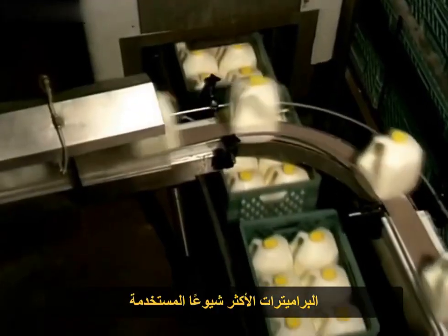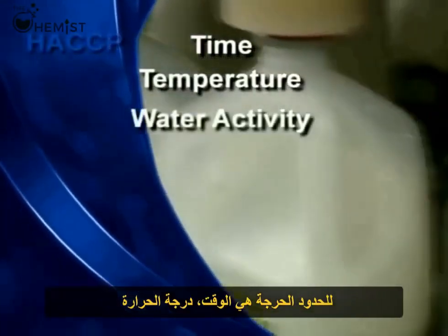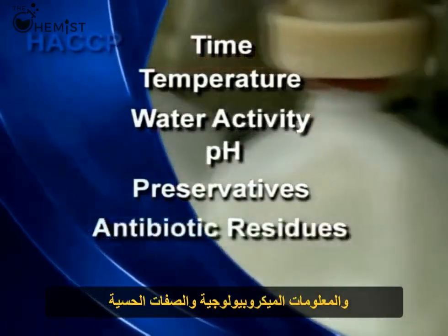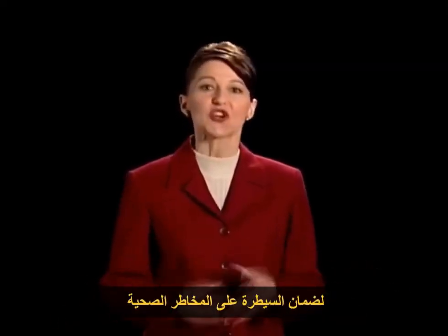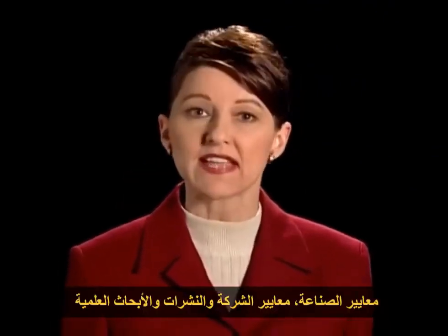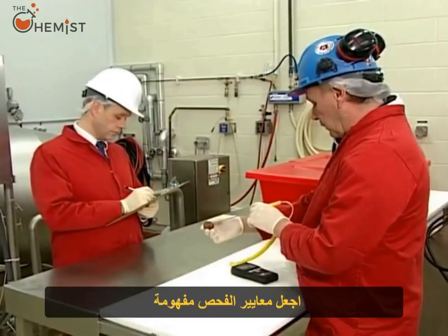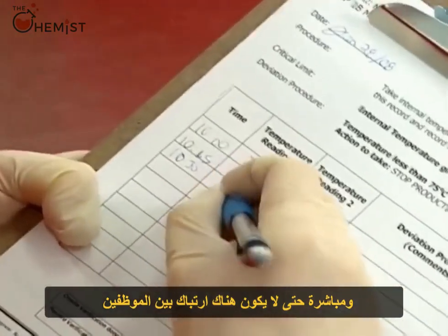The most common parameters used for critical limits are time, temperature, water activity, pH, amount of preservatives, antibiotic residues, and microbiological and sensory information. Critical limits are set to ensure control of health hazards. They can be based on government regulations, industry standards, company standards, and scientific data. Make the criteria understandable and to the point, so there's no confusion among employees.